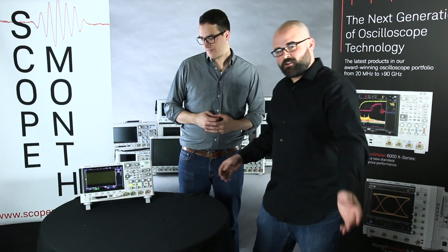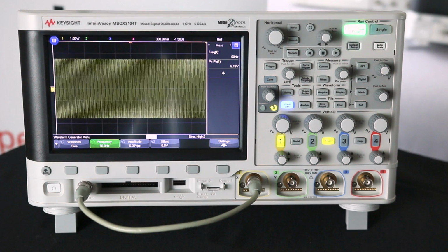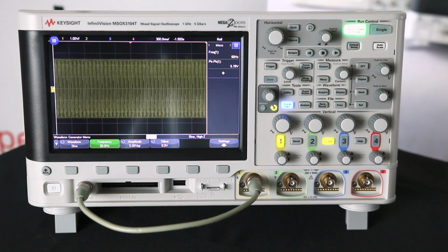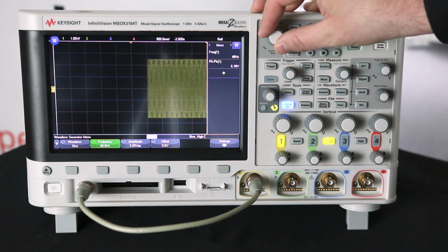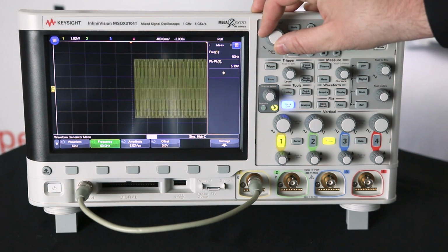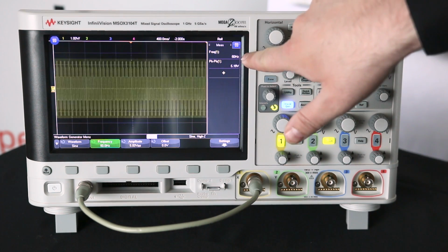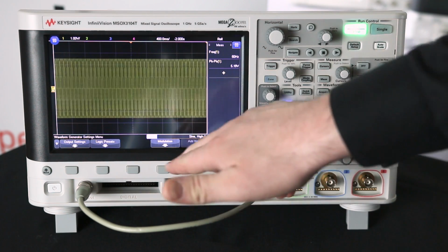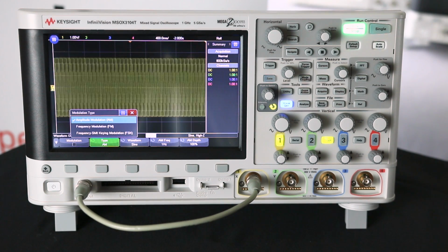Mike, why don't you give us a quick demo on the scope? Yeah, absolutely. What we're looking at here is a signal with 50 hertz. I've put the oscilloscope into roll mode, which makes it a little easier for us to visualize the signal. Let's turn on a couple different modes of modulation, and we can see how it works. The signal we have here is 50 hertz at 5 volts. There are 3 types of modulation built into our waveform generator: amplitude, frequency, and frequency shift keying.